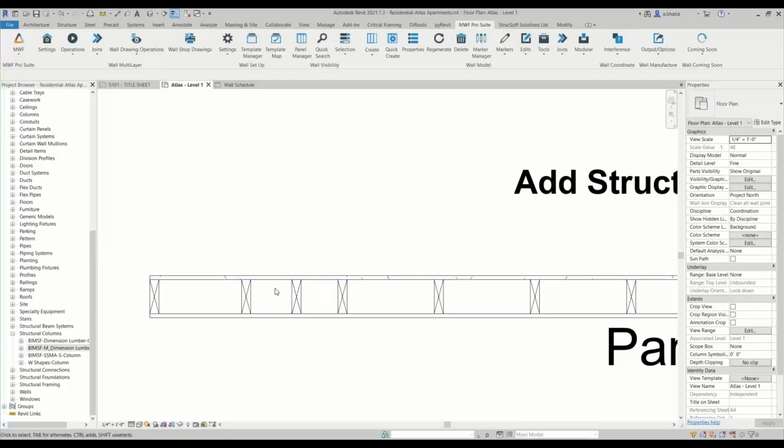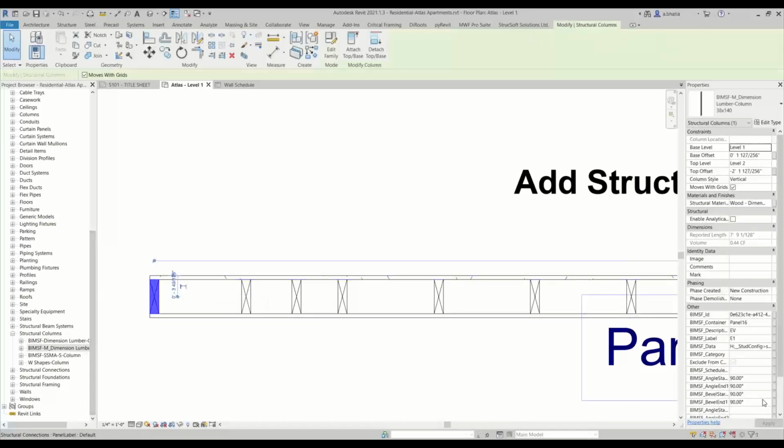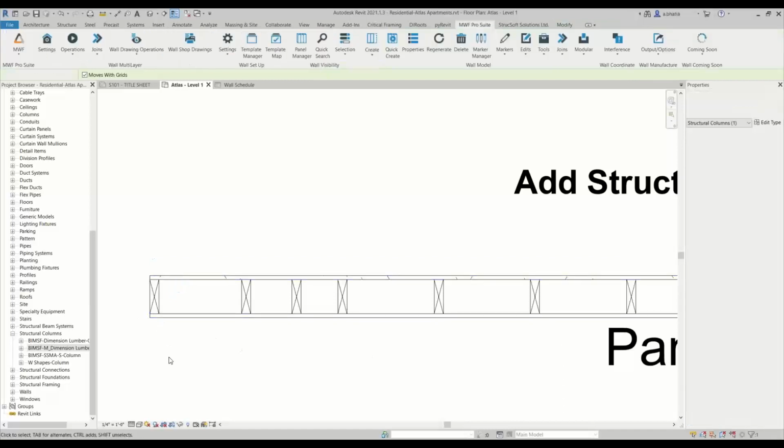Maybe you wanted to penetrate through specific types of tags only. So maybe you only wanted the whole series to cut through your vertical studs, but not your end studs. Even though this is a vertical stud, it's an end vertical, so it's an EV tag, or the description of it is EV. What that basically means is that it is a vertical stud, but it is an end vertical stud. So I have the option to not punch, or to punch, a hole in my end studs, basically.